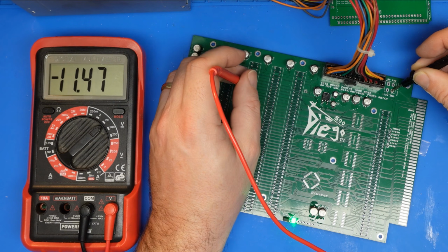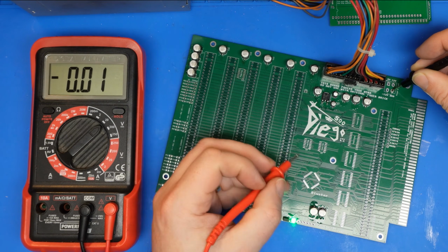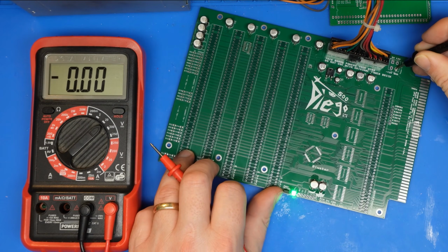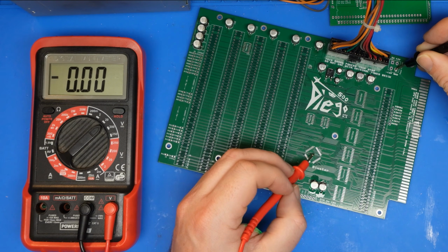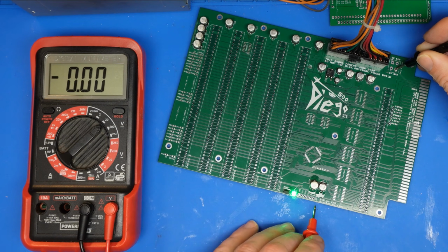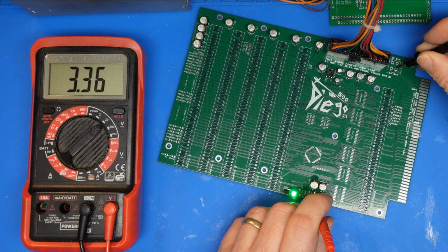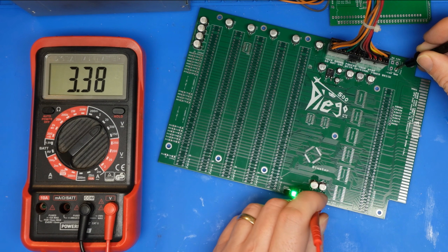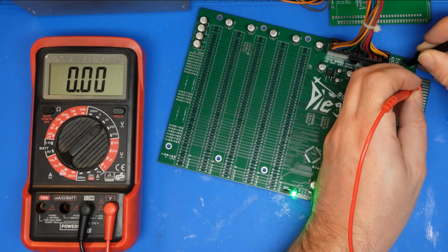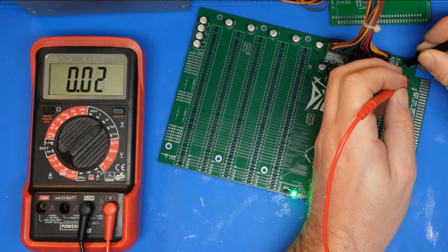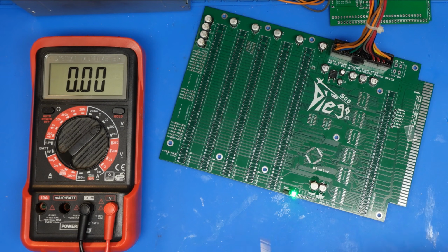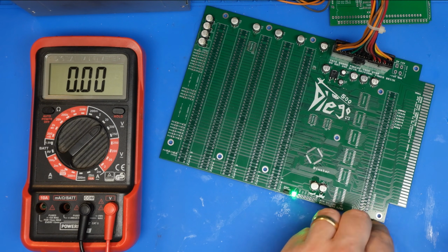That all looks good. Do we have 3.3 volt down at the CPLD? Now I'll not measure it on the CPLD itself, just because there's a ground and a 3.3 volt right beside each other on this, and I don't want to short anything. Instead though, we can measure it here just on the JTAG. And yeah, 3.38, but that's alright. So I think we're pretty happy there. We seem to have our voltages all more or less where they're meant to be. Although I have just noticed a problem on this board, so we are definitely going after another revision.